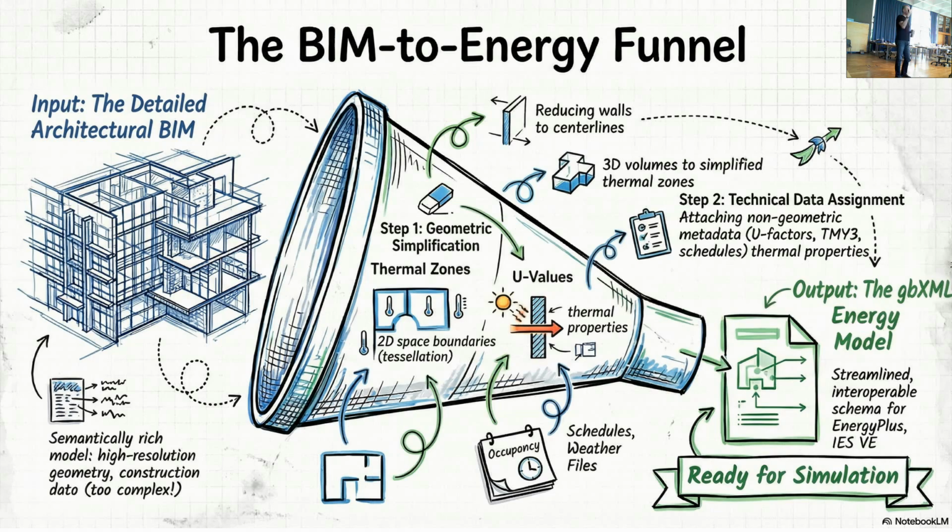Okay? So you basically feed your model, then it takes everything like schedules, weather files, occupancy. Occupancy is important. Some buildings are used 24 hours, 7 days. Some buildings are used only daytime, some offices. At nighttime they reduce the temperatures, for instance, or ventilation. Some buildings are used only once a month. You can put these into the simulations and figure out how it works in that regard.